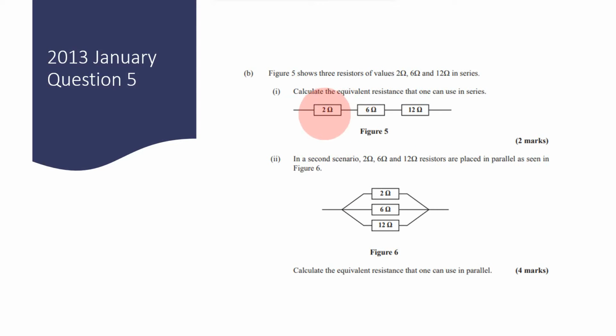Clearly, we are seeing 3 resistors in series, so we can go ahead and use our formula that says RT is equal to R1 plus R2 plus R3, and this continues to Rn, so it doesn't matter really, because we can have several or multiple resistors there. Now, for this, we'll just go ahead and put in the values, right?